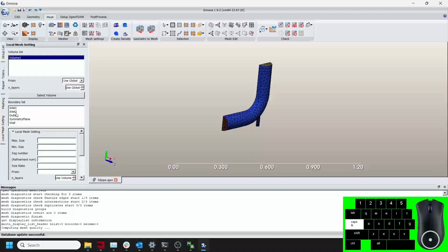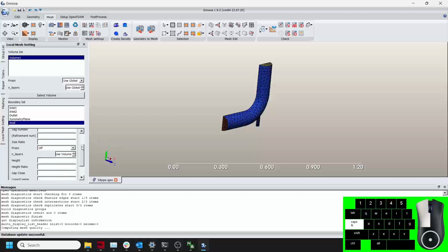After making your selections in this panel, use Apply Meshing Parameters to save your choices. Each group can individually have its parameters set, or if left blank, the global parameter settings will be automatically applied. For advanced users, a spreadsheet view of the local parameter view is also provided. That completes the parameter setup for the mesh.